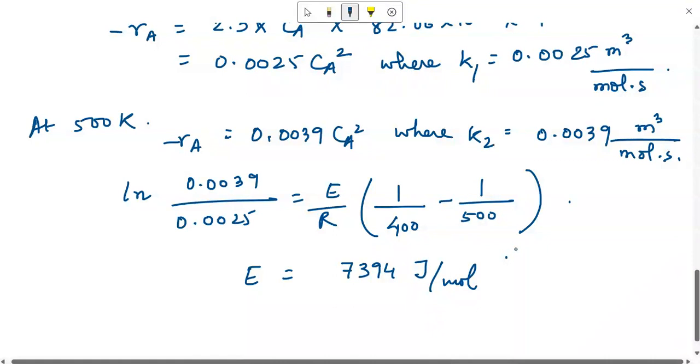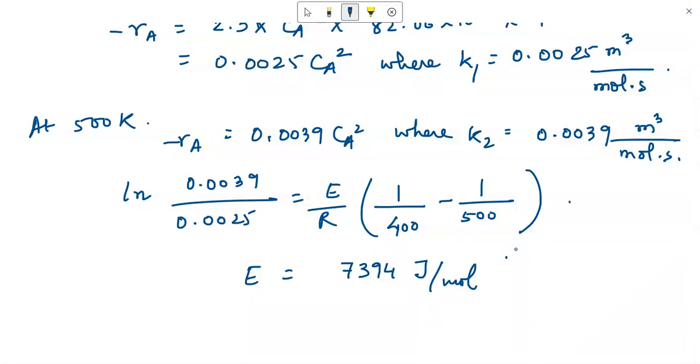In this case you got E equals 0, so you can say something is going wrong here. But sometimes you cannot detect that mistake. So it is easier to always remember that whenever you have pressure measures involved, convert them to the appropriate concentration measure and then proceed with finding the rate equation. That is it. Thank you.